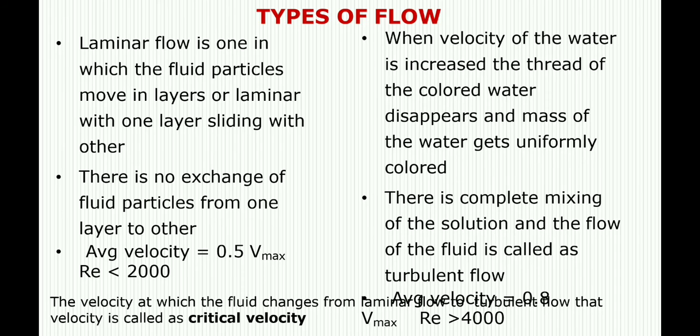Next, there is no change in the fluid particles from one layer to another. But in the case of turbulent flow, there is a complete mixing of the solution, and that flow of the fluid is called turbulent flow. The average velocity for laminar flow is 0.5 Vmax. In the case of turbulent flow, the average velocity is 0.8 Vmax.